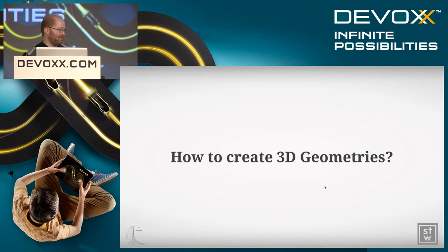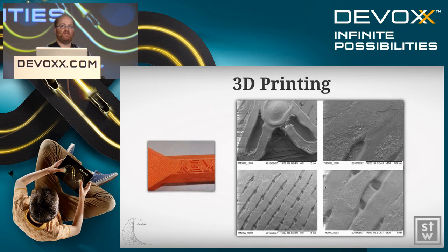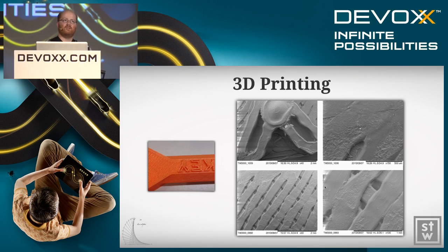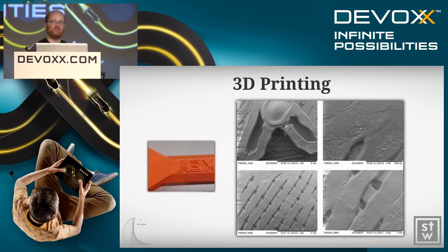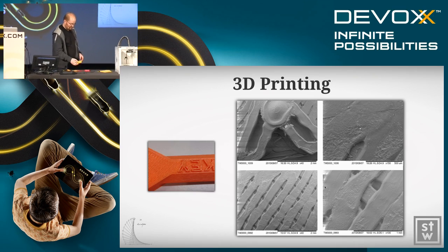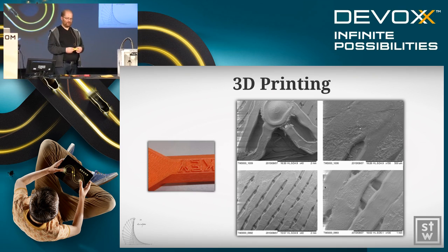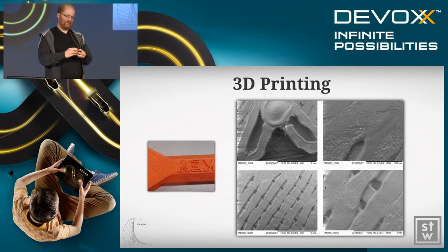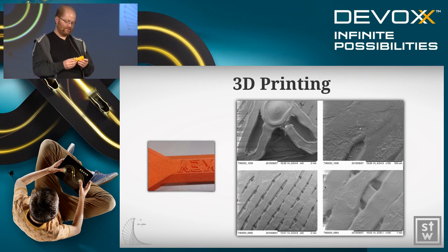So this technology is called FDM. So we are adding material on top one of another. So usually, if you do machining, you are reducing, subtracting stuff from a metal block or something, and this is what's used in industry. But for prototyping, it's actually much better to use something like additive, adding plastic, one layer on top of another. So this additive manufacturing, that was the word,